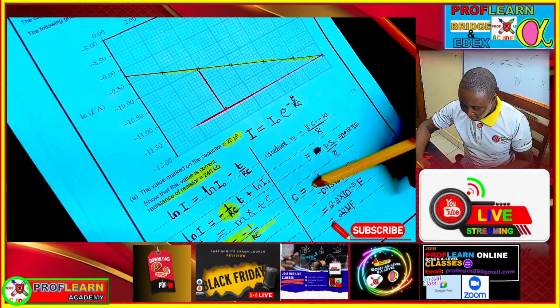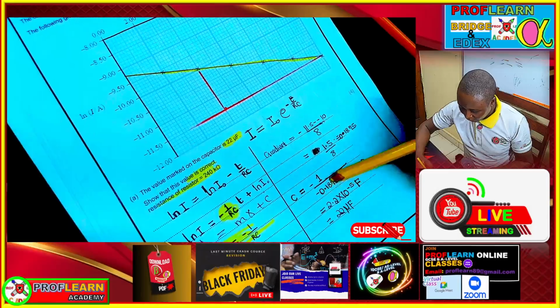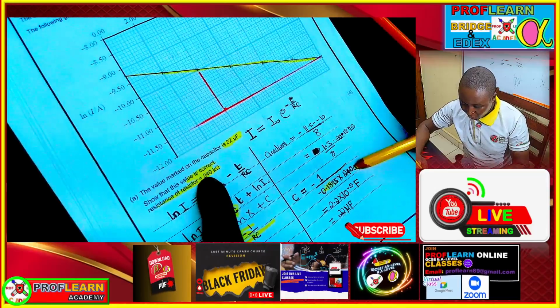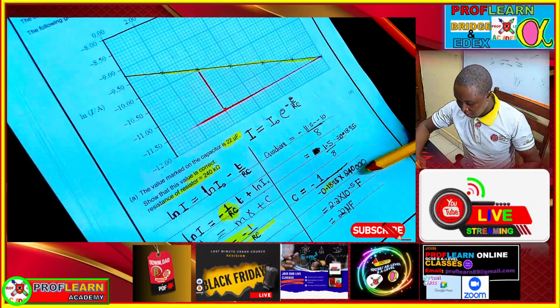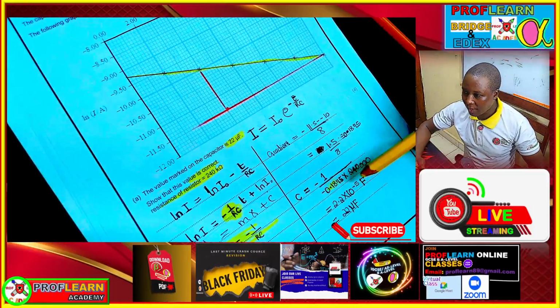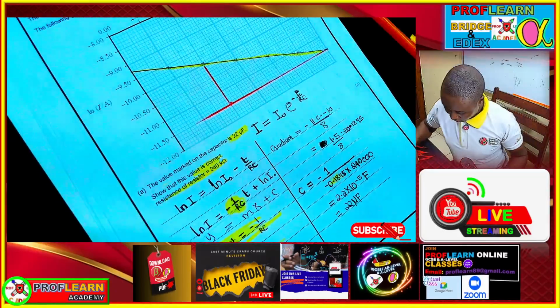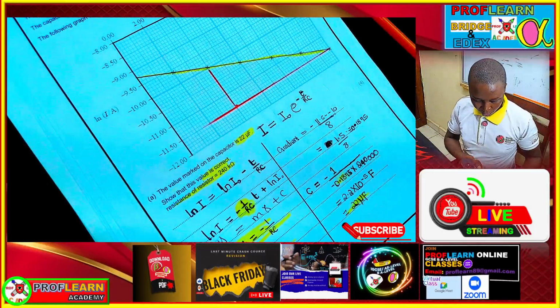You get negative 1 over negative 0.1875 times the resistance, which is 240 kilo. Most students missed this because they never remembered the kilo on the resistance. Then if you work it out, you get 2.2 times 10 to the power negative 5. If you convert this to microfarads, you get 22 microfarads, which is correct, and which we have shown at this point.